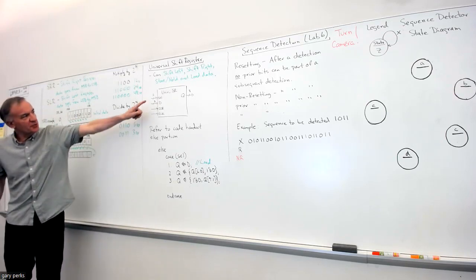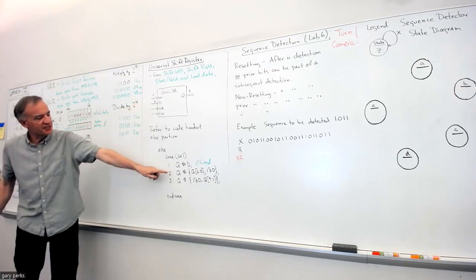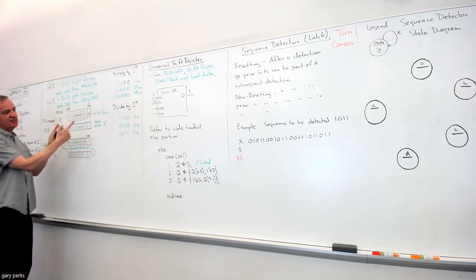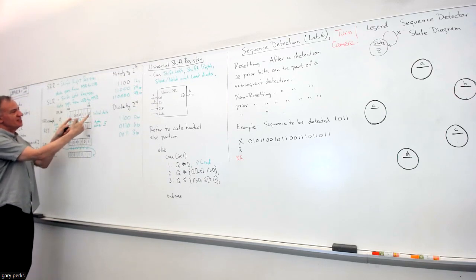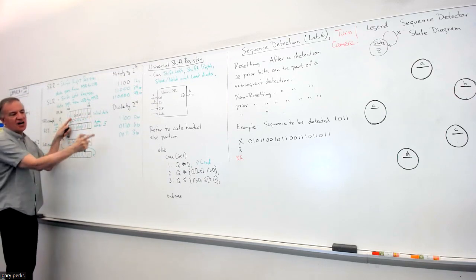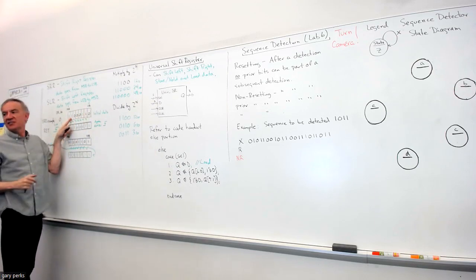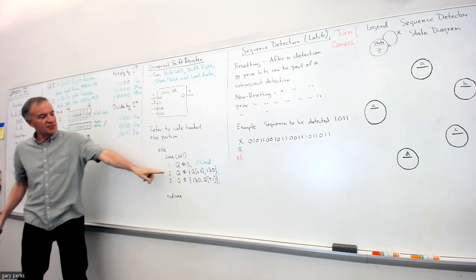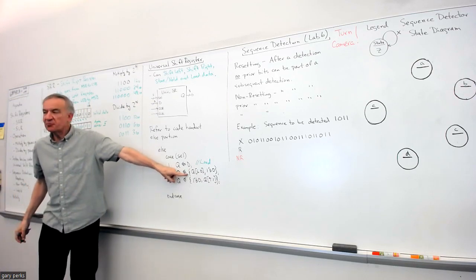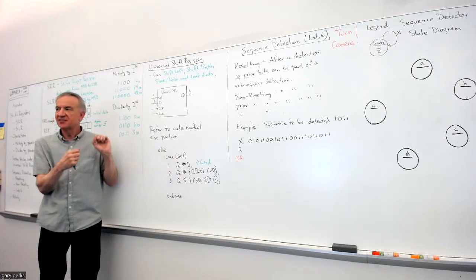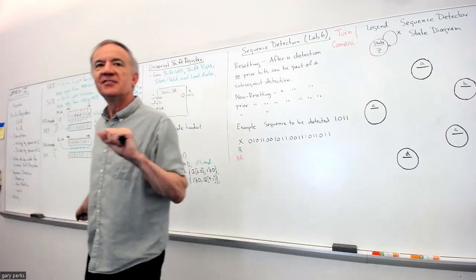So when we put a select of 2 on this universal shift register, Q is going to be assigned bits 6 through 0, right? So it's going to be assigned these bits along with a 0 tagged on to the end of those 7 bits, right? Because remember we talked about what the braces do in SystemVerilog? What do we call this when we have the braces? What are we doing here?